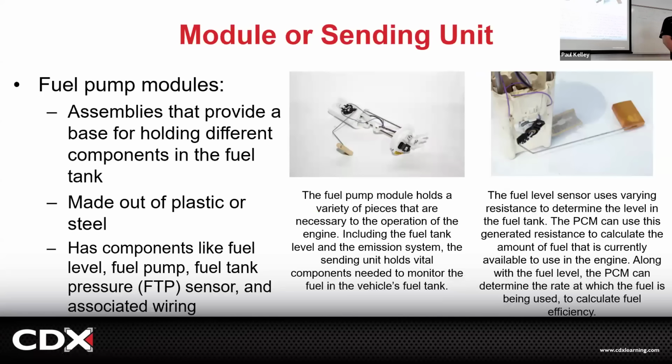Cool. And then different types of modules, right? So this one's pretty typical. You can see the fuel level sensor. You can see how the fuel level sensor has this piece of plastic we call the float. For some reason, if the float had a hole, it will no longer float. It might give you the appearance of an electrical failure, but actually it could literally be a hole in the float. The good thing is if you get a new fuel level sensor, it comes with the float and the rod and the actual sensor right here, which is a variable resistor grid, like a carbon grid.